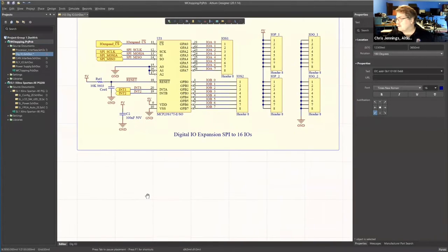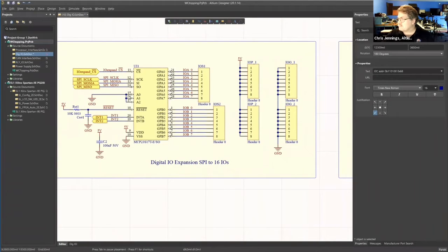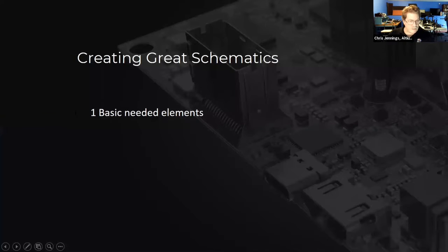Again, simple things like net labels, very critical, especially something important like reset. I could also see things like buses. That's a very useful thing to have. It just makes it neater. It makes it cleaner. And when you have buses at a higher level, what you end up having is a much cleaner view of how data flows around, how your address flows, and all of your control signals. Again, communicating design intent is critical.